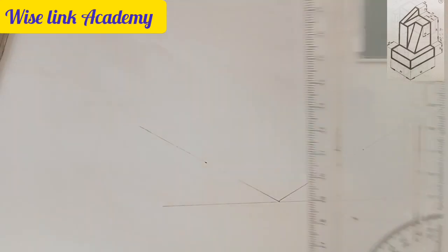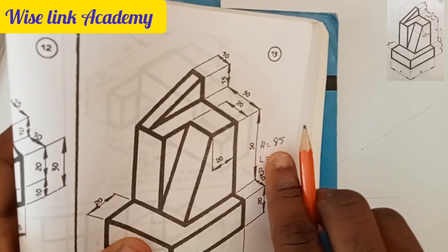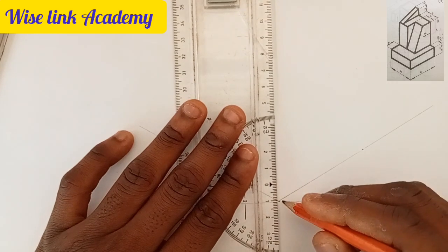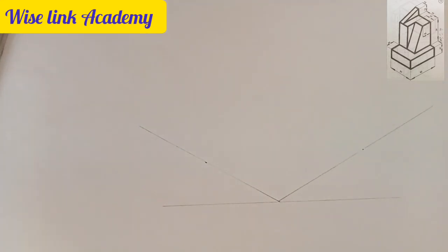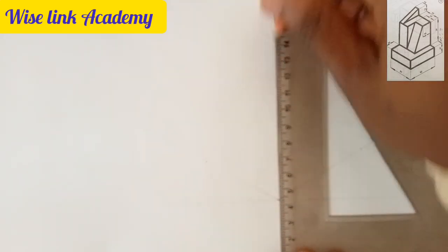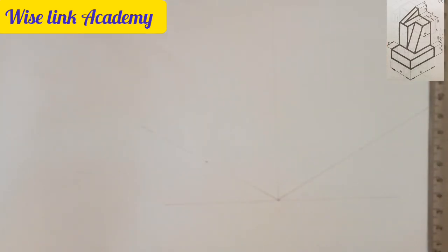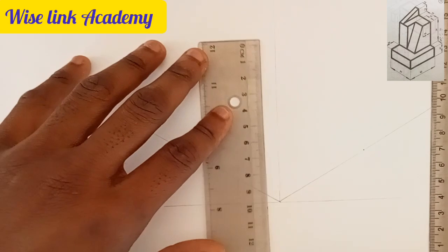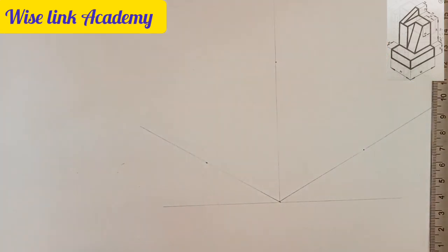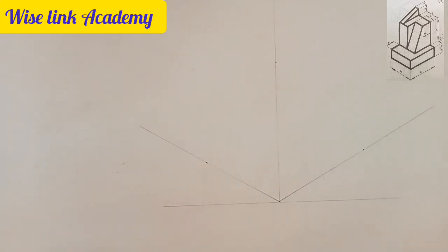So don't forget, I said that the height is what? 85. To measure 85 from the middle here, before I even do that, draw 85. You place your set square very well, and you put this to the middle. You draw it upward. You can see that. So our height is what? 85. So we measure 85 from here to here. As you can see, just indicate your point first. That's the first thing to do. Indicate your point. Let me show you what I'm doing.